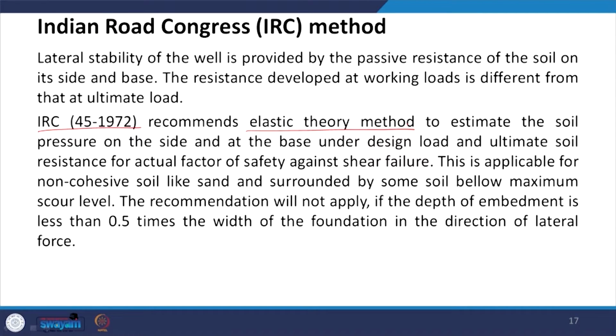So, you have two cases. One case is to estimate the soil pressure on the side and the base under design load. The other is under ultimate soil resistance for actual factor of safety against shear failure. When you are considering the shear failure, then ultimate soil resistance will be considered. This is applicable for non-cohesive soils like sand, surrounded by soil below the maximum scour level.